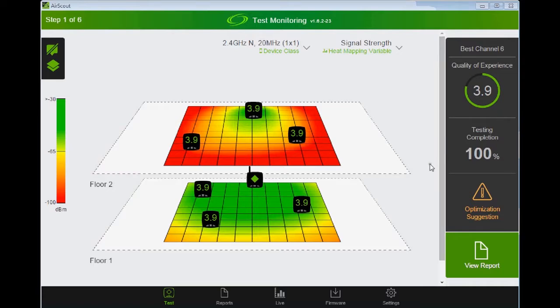Interference is caused by devices emitting in the 2.4 GHz and 5 GHz 802.11 radio spectrum and is a common problem. This includes devices like microwave ovens, cordless phones, Bluetooth devices, wireless video cameras, wireless game controllers, Zigbee devices, fluorescent lights, and more.